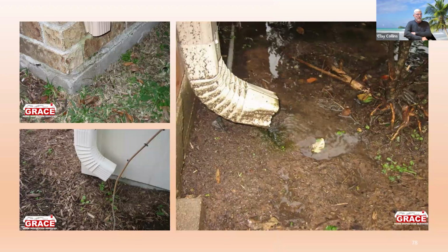And here we're talking about those downspouts. No elbow, no splash block. The one on the bottom left, they have directed the water alongside the foundation where it will cause erosion and stay against the foundation. And then you see the erosion on the rightmost picture, and that's not recent. You also look and see that they have plenty of room for some more sod there. They've even eroded all the soil away from the roots of that tree, or that shrub. I'm not sure what kind it is. There's a white piece of PVC alongside the house, and I don't recall what that is.